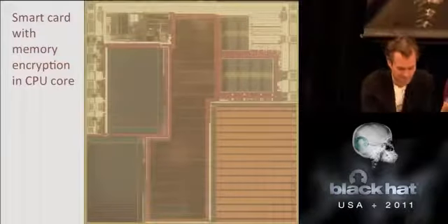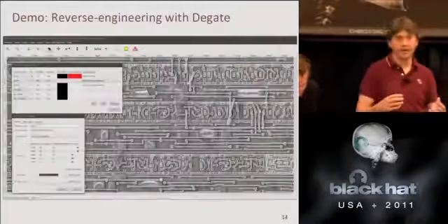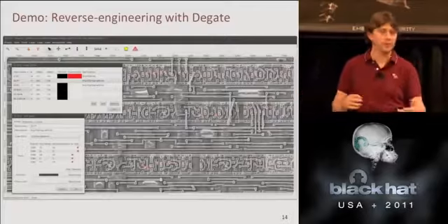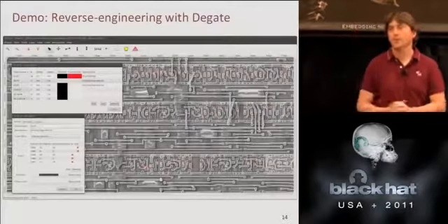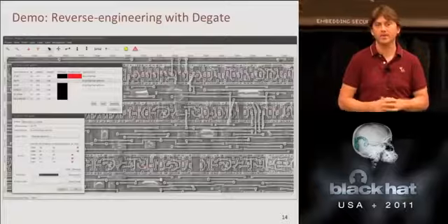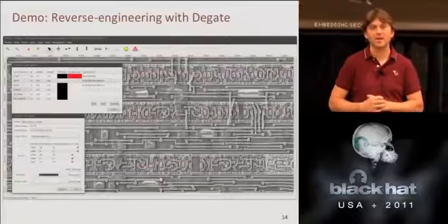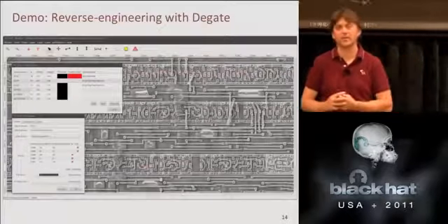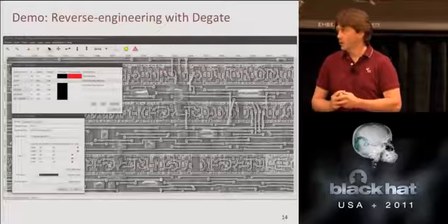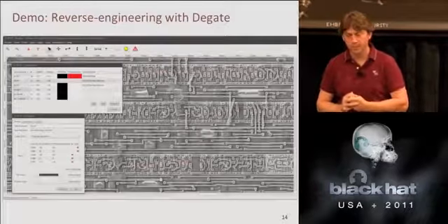And remember, this is so you can then optically read out that ROM and not have to use any needles, because maybe you don't have needles, but you have access to microscopes. Right. And optical microscopes are good down to about 150, 180-ish. 180, I'd say, is about probably the best for most people. Even with oil and all. Yeah, wet immersion, some type.